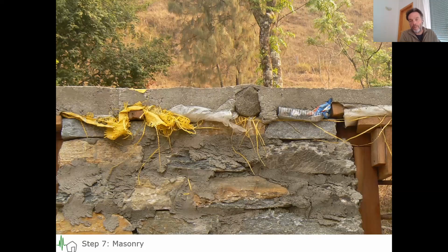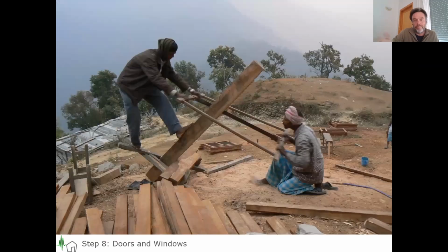So this is then something that we see, I don't know, after a few weeks at one of the schools. Then all of a sudden they go back to this quality. And then we learned that the group of masons went to the city for another project, and then new masons came here, and so we had to teach them again how it was supposed to be done. But this one we broke down. I mean, this is going to have zero, and this is an important one. This is at lintel level, so this needs to be removed, and we do it again.